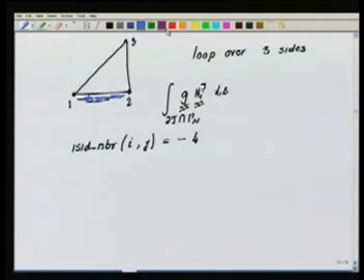You see n3 becomes 0 all along this edge. So the only non-zero shape functions on this edge are my n1 tau and n2 tau. Okay, so n1 tau and n2 tau are the only shape functions which are non-zero on this edge, which is my first edge of interest. So given the edge, I can easily find out which of the shape functions of the element are non-zero on this particular edge. Okay.